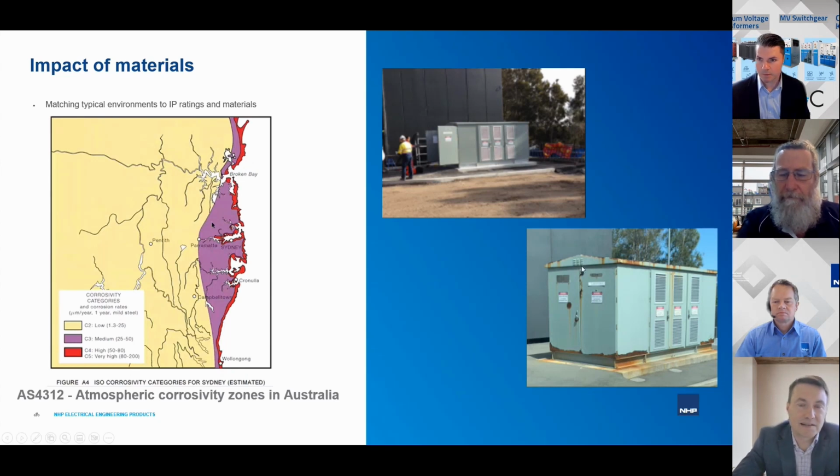Yeah, that's exactly right, and we have heard this information from the experts on the corrosion, explaining in examples like this one what exactly happens, because when we look at the photos closer, you can actually see that the powder coat itself is not damaged, but the rust happens underneath the powder coat. And the explanation for that is, yes, the standard powder coat material is a porous material. So the moisture slowly penetrates through that, and that causes the material underneath to start rusting.